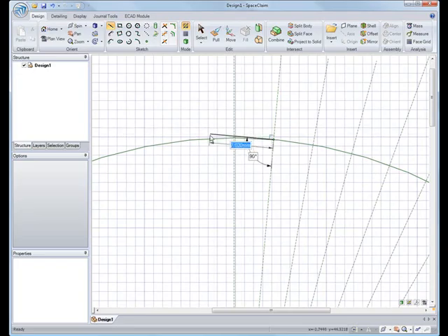So we want to make a tangent line every 5 degrees, and we want to make it pi times the diameter, which is 100, times the angular measurement, which will be 5 degrees. So we're going to do 5 divided by 360 and hit enter. That will give you a point on the profile of the involute, which we will create with a spline.